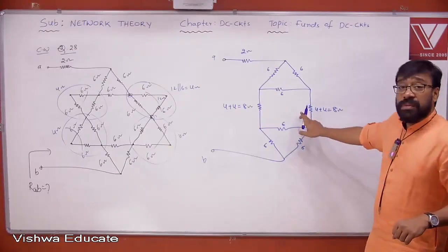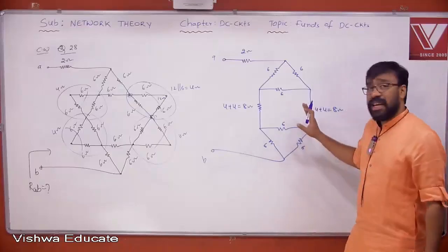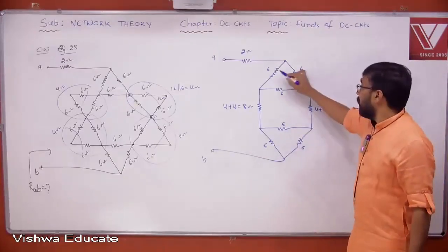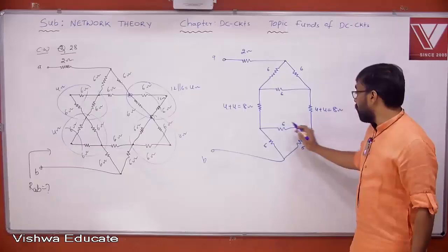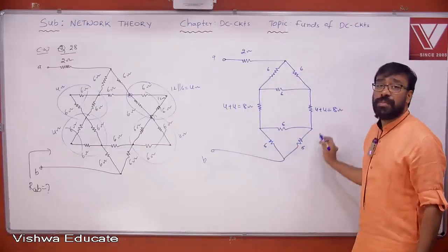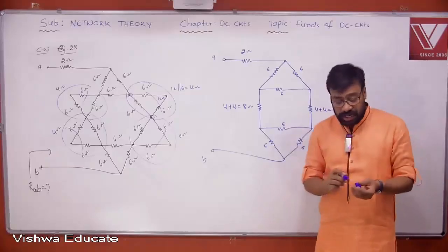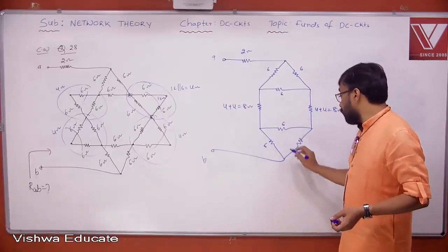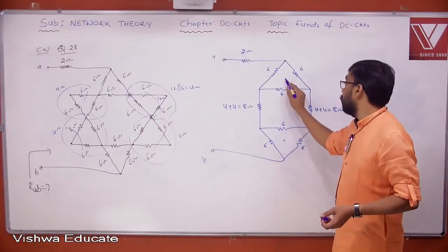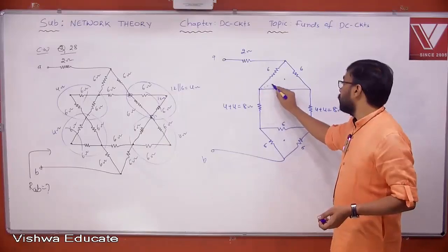Look at this case now. After drawing this, we understand that it is unavoidable. Neither series nor parallel. All elements are neither series nor parallel. You have to go for star delta transformation. Now let me apply star delta transformation for this because equal values are there. I think I prefer that. Like this.